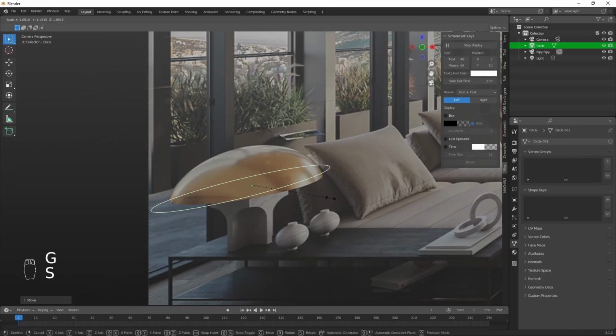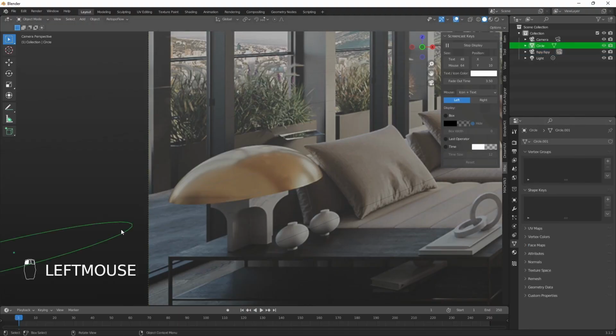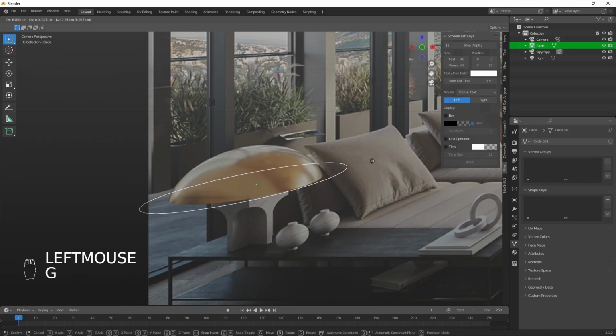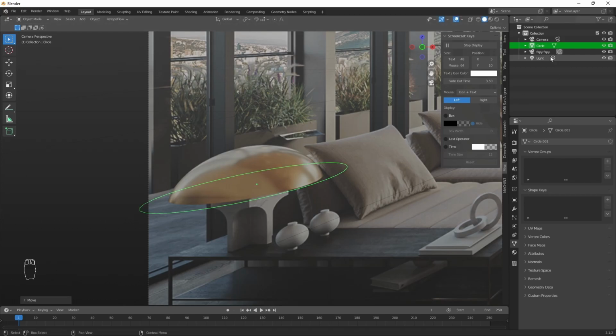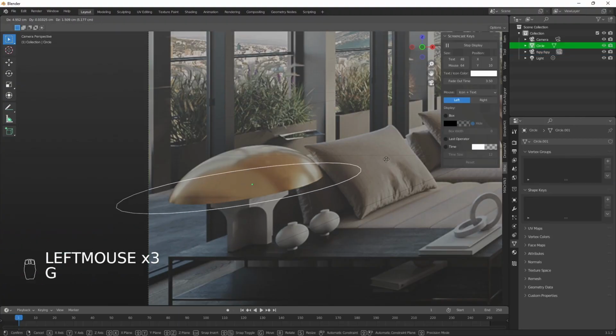Because the circle is still stretched too much, I need to lower the field of view. I'm going to switch the unit to focal length though. It doesn't matter at all, but it's just my personal preference. Okay, so let's type a larger value. By the way, every time you change it, you need to reposition the reference shape. Don't worry, it's normal. 10 is still not enough, so let me try 15 and...